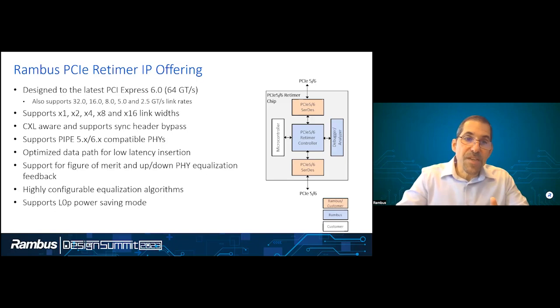A couple of things about the retimer IP: it is CXL aware, allowing the CXL synchronous header bypass supported by the SerDes, optimizing the data path for low latency insertion, with highly configurable equalization algorithms, and the IP itself supports the L0p power saving mode in PCIe 6.